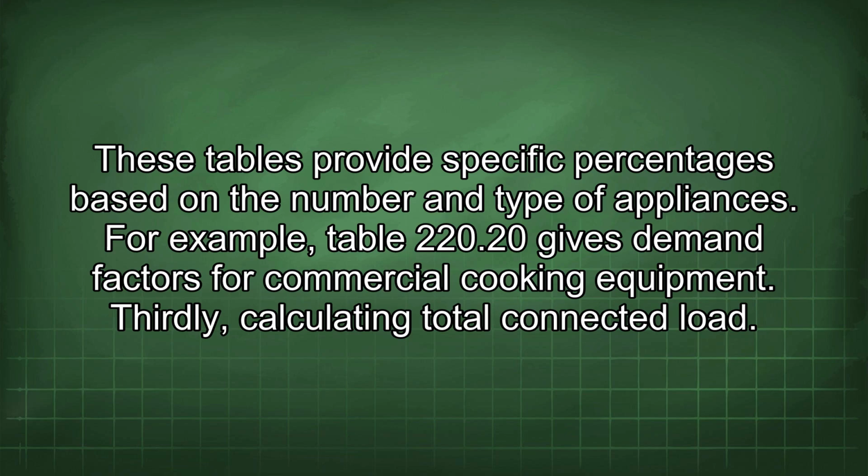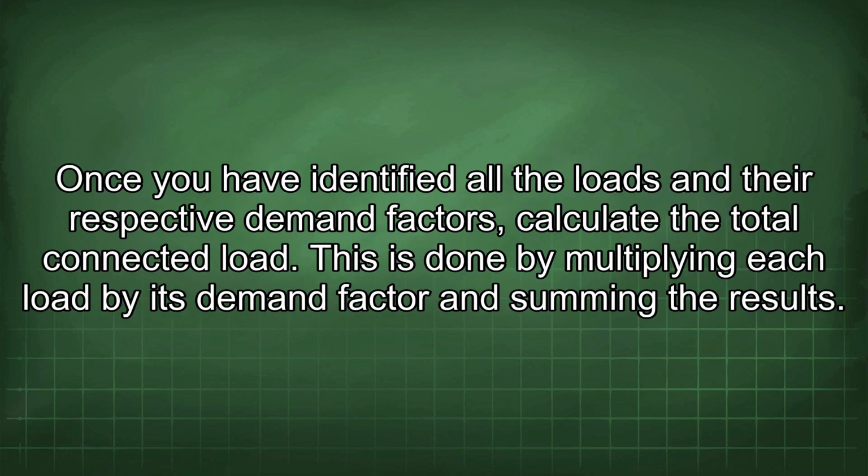Thirdly, calculating total connected load. Once you have identified all the loads and their respective demand factors, calculate the total connected load. This is done by multiplying each load by its demand factor and summing the results.